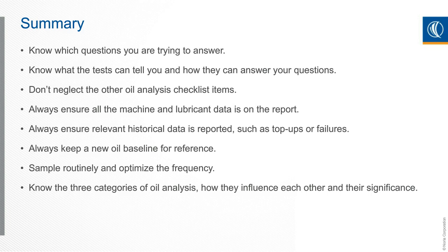Always keep a new oil baseline for reference. I've said that several times. Sample routinely and have an optimized frequency. I didn't talk about that very much, but it's an important aspect to know. Okay, well, we're going to be sampling on this machine, but we need to sample just enough to where we are able to detect a potential failure, an incipient failure, or maybe even better, a root cause that could eventually lead to a failure before it starts to get worse.